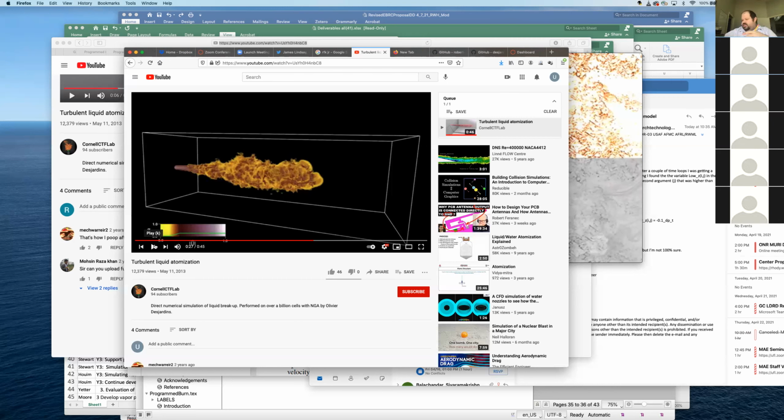And the multi-phase community will call those direct numerical simulations, even if they aren't fully resolving the turbulence. So here, I don't know if they're doing a DNS in the sense of turbulence, but in terms of particles, they are. And they are certainly at very fine length scales, because those droplets being stripped off are really small. So in all likelihood, if they're not an actual turbulent DNS, they are really darn close to that. Okay, so just be careful with that.